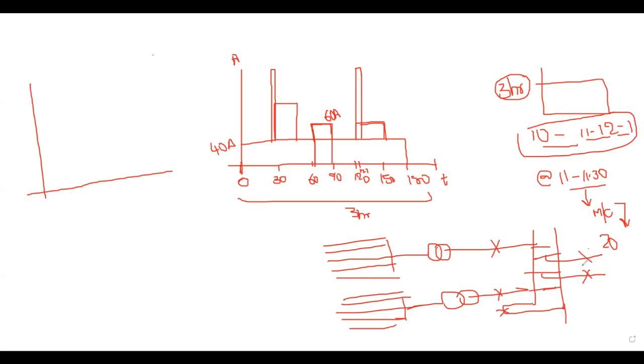So we will see what is the maximum worst condition in the substation. In the substation, we are not having machines or any motors, right? So these DC loads are mostly relays, mostly control and protection. So we are considering the worst condition that a busbar differential protection operated. If a busbar differential protection is operated, then all the breakers connected to this bus should trip at a time. How many breakers? 1, 2, 3, 4, 5 breakers are tripping at a time.